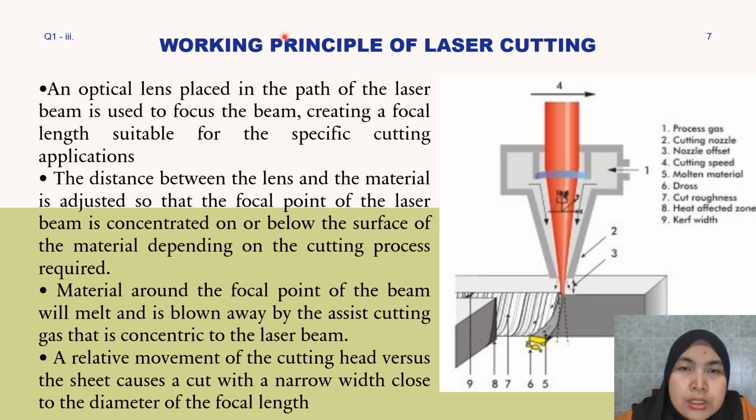Laser cutting starts with generation of a high intensity laser beam, achieved using a laser resonator, which stimulates the emission of photons in a coherent and collimated manner.